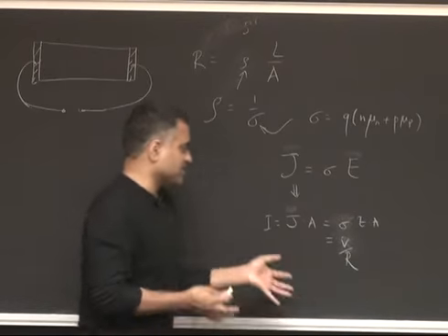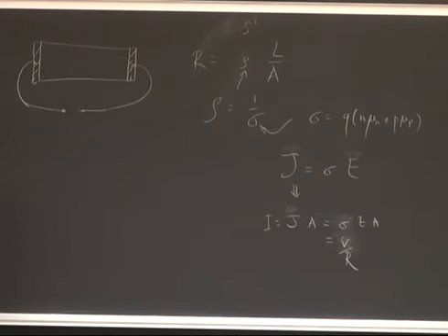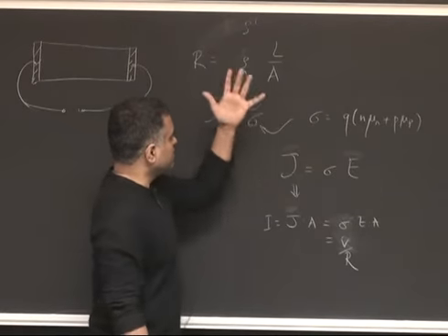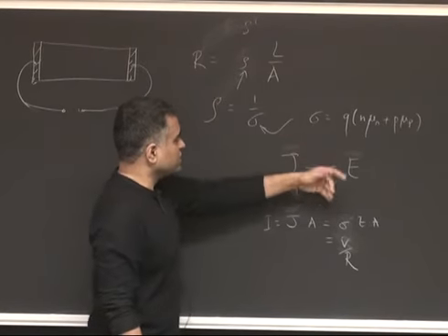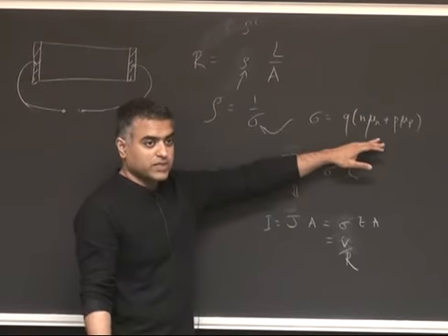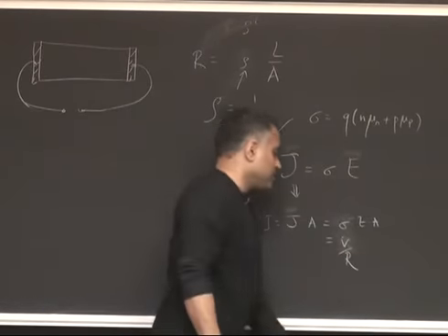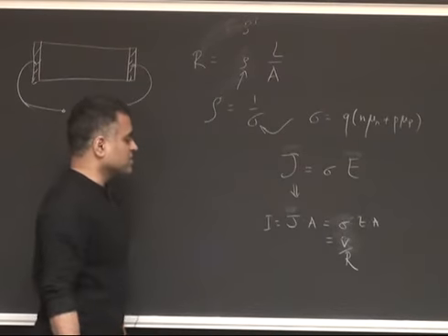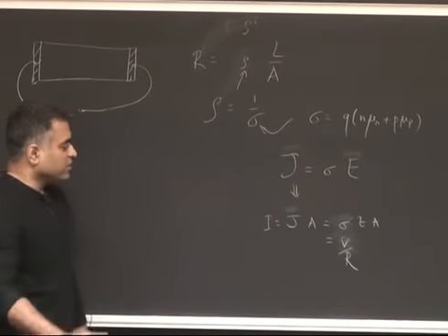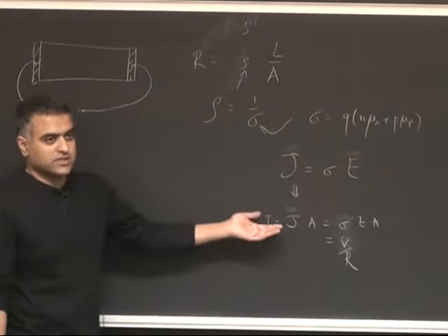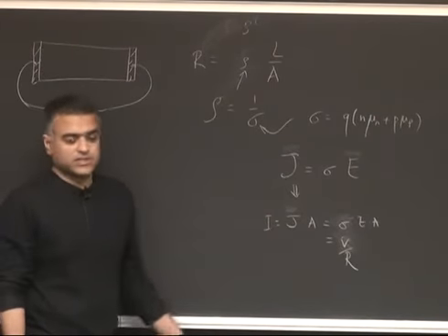And we know it's valid in a certain regime. If you apply very high voltage, high electric fields, current saturates, you deviate. If you have very small dimensions, transport occurs ballistically and not quite by diffusion, so you deviate and all that. So there are deviations, but for dimensions which are a few microns and voltages that are not thousands of volts, this is a reasonable model.